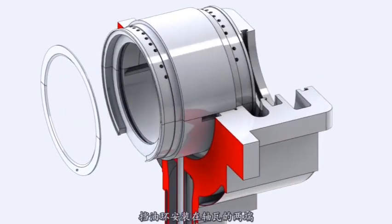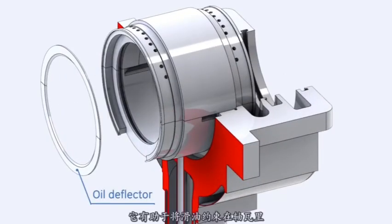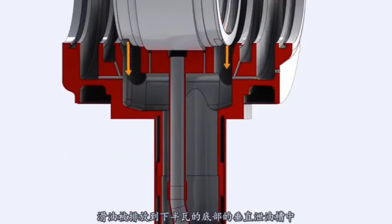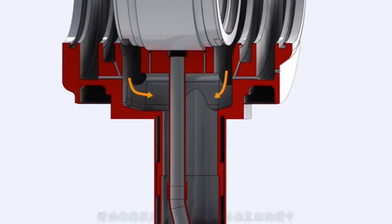Oil deflectors are mounted on both ends of the liner to help contain oil inside the liner. Oil is drained through the vertical drain slots at the bottom of the lower liner half to the lube oil drain cavity, down to the oil drain piping.